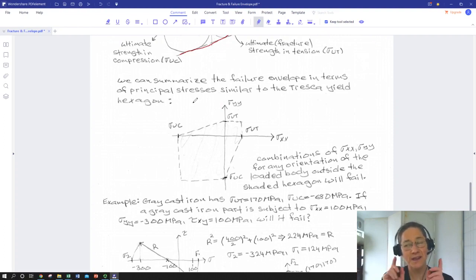So we can take those tangent lines and basically summarize them by plotting normal stresses against each other. So we're expanding what we did in uniaxial in the lab to maybe a biaxial stress state out in the field, because things are rarely loaded just in uniaxial tension. So we're going to suppose we have a plane stress state, which is a little bit more common, out in the field, and we're looking at the different combinations of applied stress in the X and Y where you're not going to get failure. So we'll basically plot a Tresca envelope where we'll plot the ultimate tensile strength in both directions.